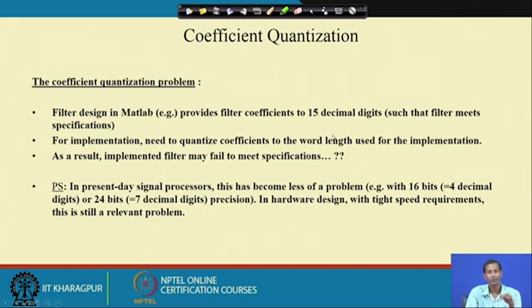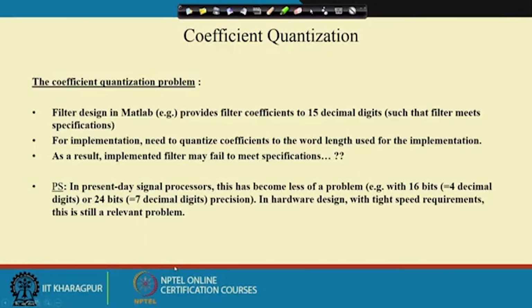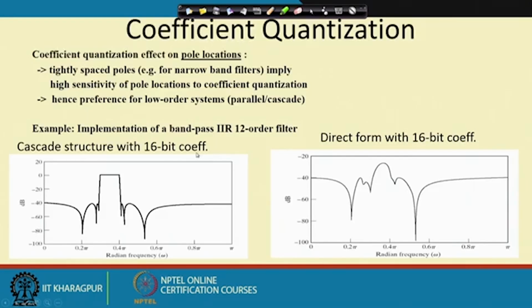We had taken the example of an FIR filter at the time. So, we need multiple constant multipliers where we have to consider a multiplier bit length of 60 bits to meet the corresponding specification. 60 bits requires a lot of hardware, right? So, to reduce that, we will see what the optimum word length is.